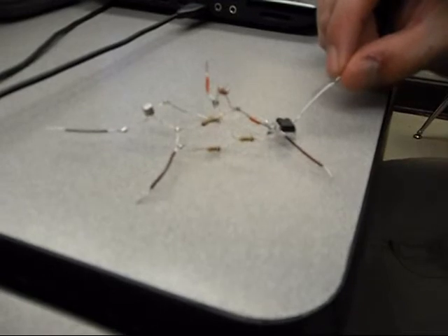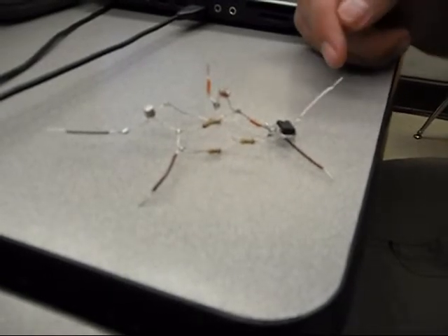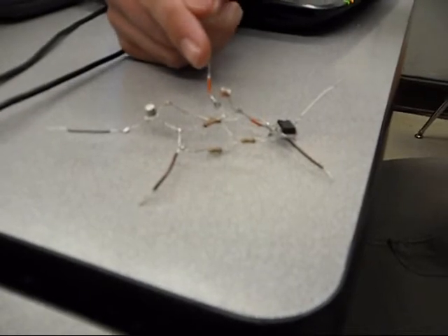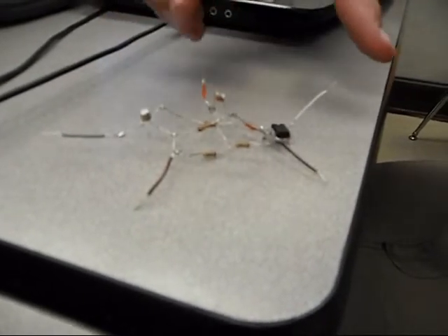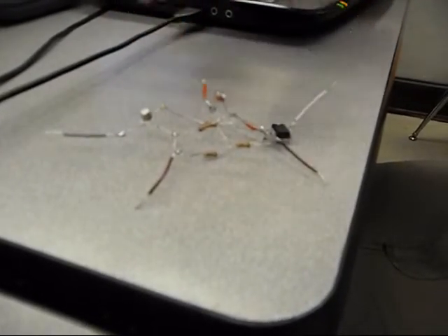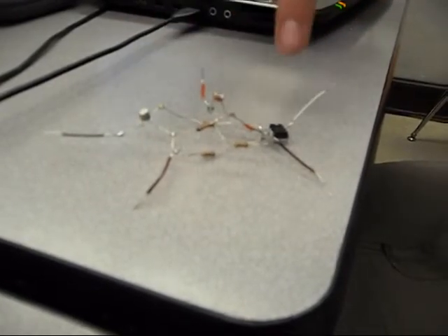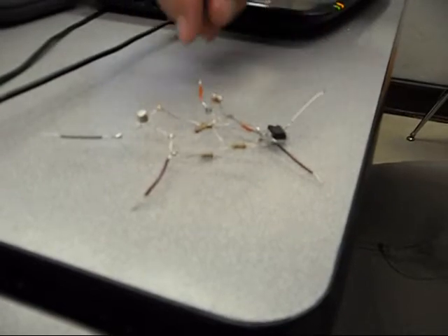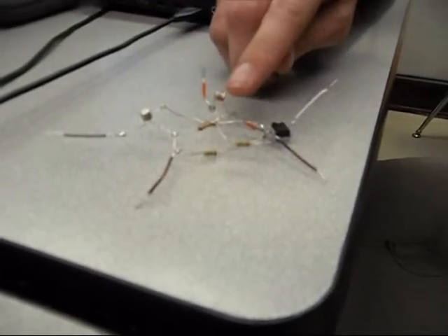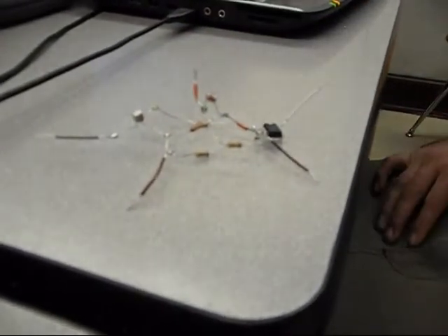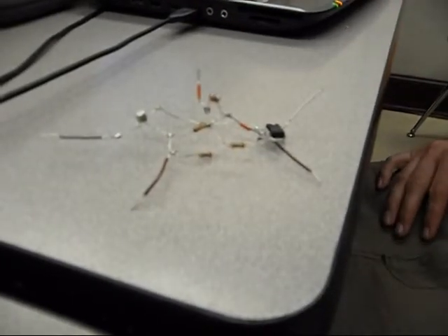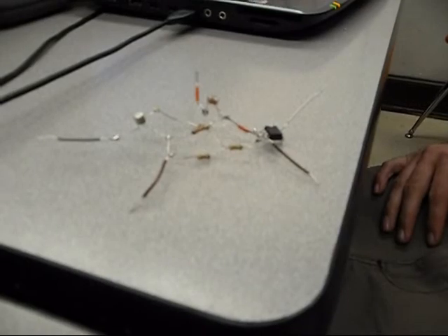This white wire at pin 8 is going to positive 12 volts, and this little orange wire is also going to positive 12 volts, but separately. They're not going to the same 12 volts, or else that would mess up the chip, the op amp. And this light-dependent resistor is going to be protruding from our final container, and that's what's going to be our sensor in the circuit, turning the LED bulb on and off.